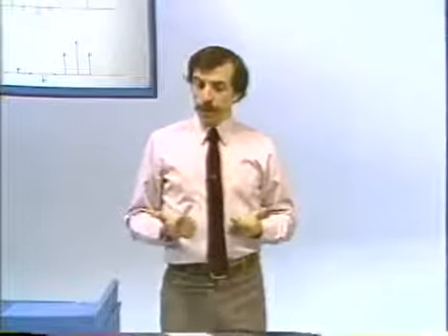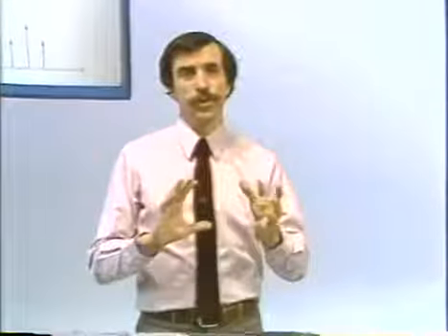We saw that there are some important differences between continuous time and discrete time, and the difference relates to two aspects. One is that in discrete time, we have a discrete representation in the time domain, whereas the independent variable in the frequency domain is a continuous variable. Whereas in continuous time, for the Fourier transform, we had a duality between the time domain and frequency domain.